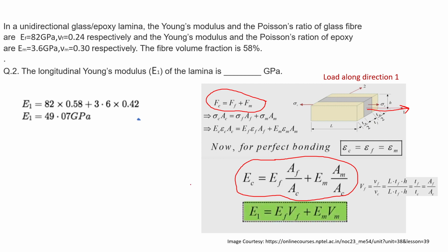So, in the question, we have to find the longitudinal Young's modulus E1. So the equation will be equal to EF VF plus EM VM.